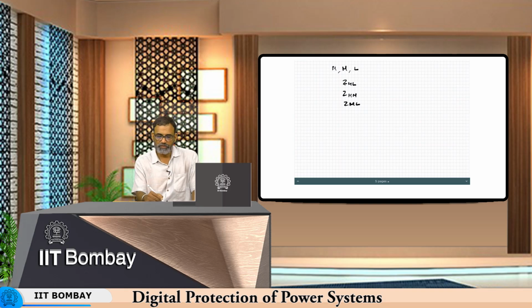Okay. So, the definitions are the same. That is the leakage impedance, which is calculated in a similar way as for a two winding transformer, only that the third winding is left open circuited. So, you will be given some values here like this. Now, you have to find ZH, ZM and ZL from the above three values.